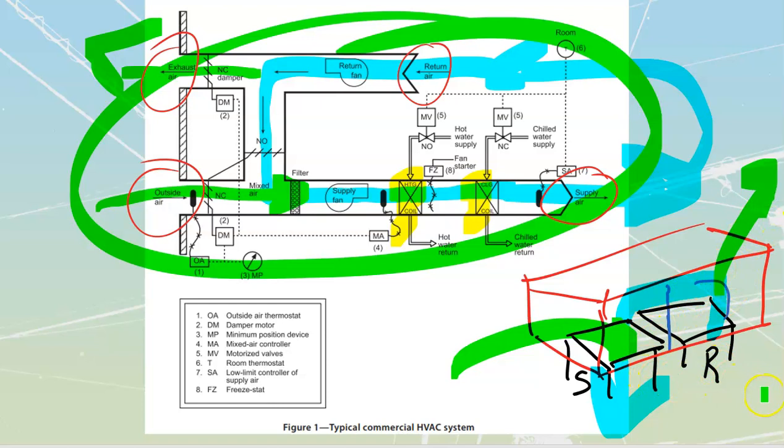Inside of a lot of smaller commercial, we're going to have multiple rooftop units for different zones. Inside of a larger commercial that's got a built-in, we're going to have one master controller, and then we're going to individually control coils inside of the zones, whereas this, if I'm dealing with rooftop units and I've got a building that's got, let's say, a little bit of warehousing and some office space and some manufacturing area, what I'll do is I'll have a rooftop unit for each one of those, so that the office temperature can be separate from the warehouse temperature, which can be separated from my manufacturing temperature.